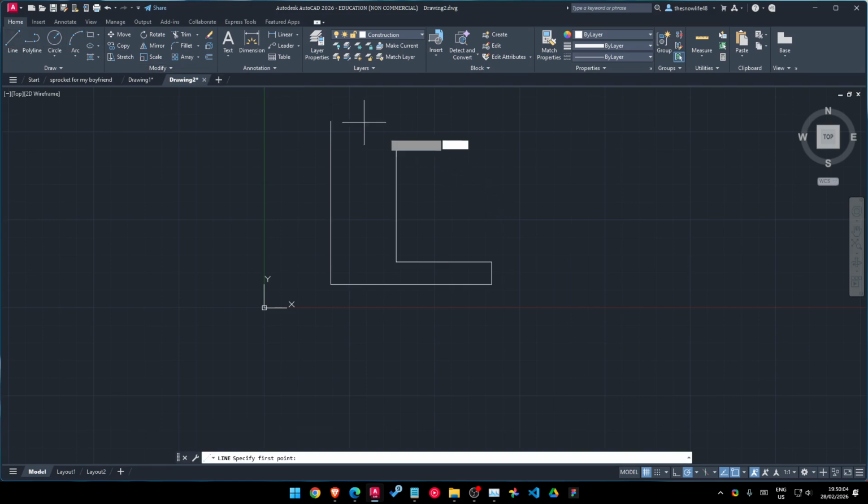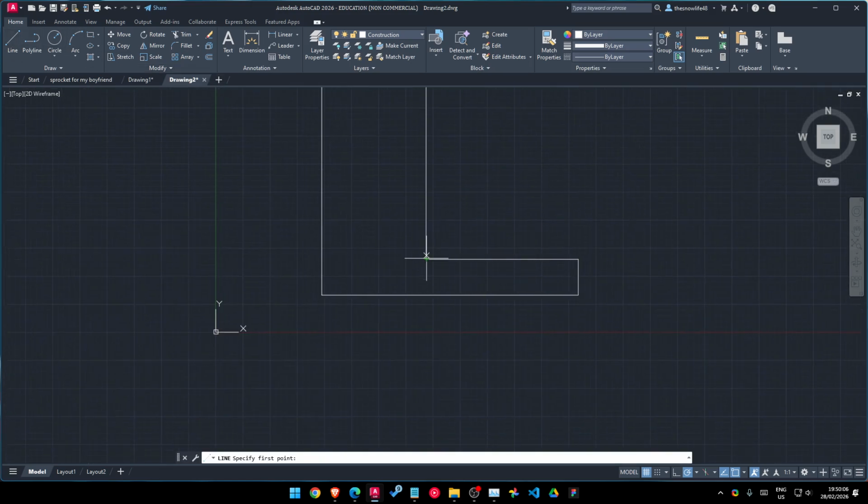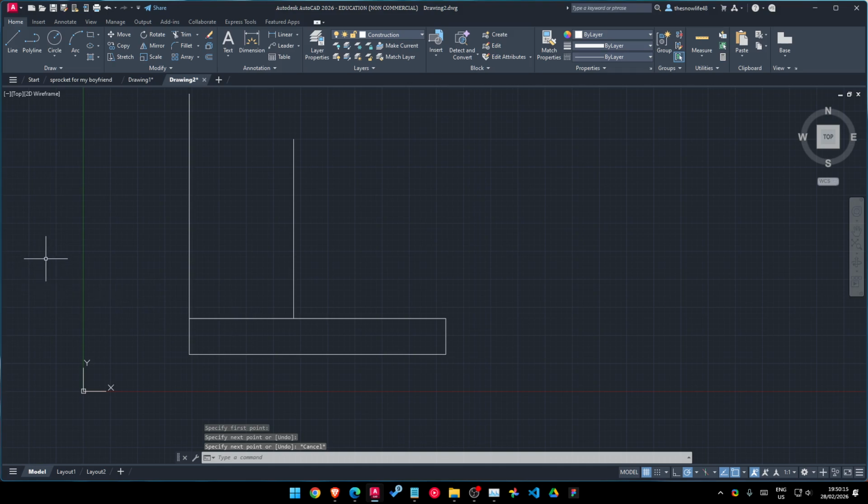Now also we need to connect these two. Circle using tan, this, and this, and you get a perfect circle. Now center and radius needs to be, so when you select a circle, it's not going to snap at the center, so you have to hover over the boundary of this circle, and then this plus sign appears, and 10.